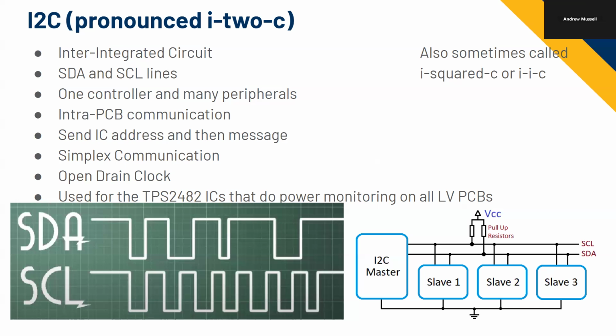Because a capacitance charges with Q equals CV, right? So the current is equal to the capacitance times the change in voltage. So if we had small current noise and a smaller capacitor, it would change your voltage a lot more. So if you had no capacitance, this bus would change really easily, which means it takes less work to change it. But that also means noise has more power over it because the strength of your noise isn't changing. So if I make it easier to move this node around, then noise will move it around more.